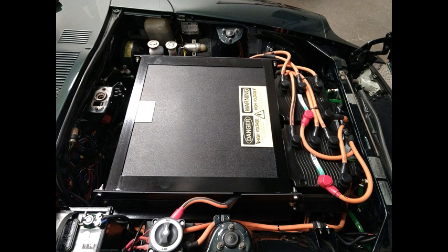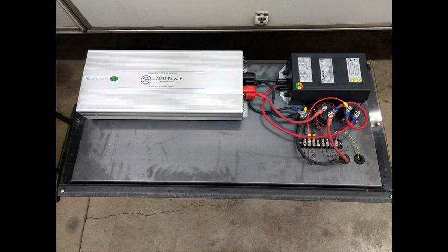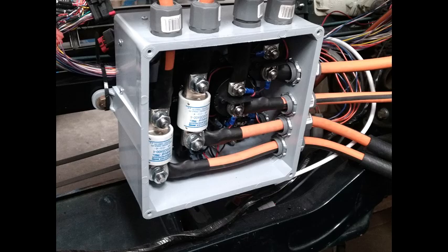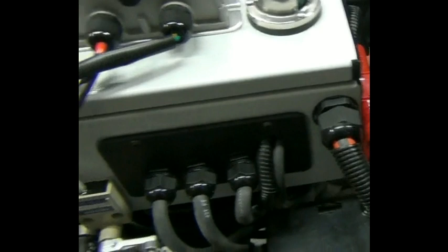All of your wiring and cables should be secured so they don't rub or wear against any surface or object. Also, remember not to run wiring near anything that gets hot or in a fashion where it may get damaged. When passing a wire or cable through sheet metal or any other surface that could gouge or damage the wire, be sure to use a grommet or a cable gland nut to protect the wire from damage.